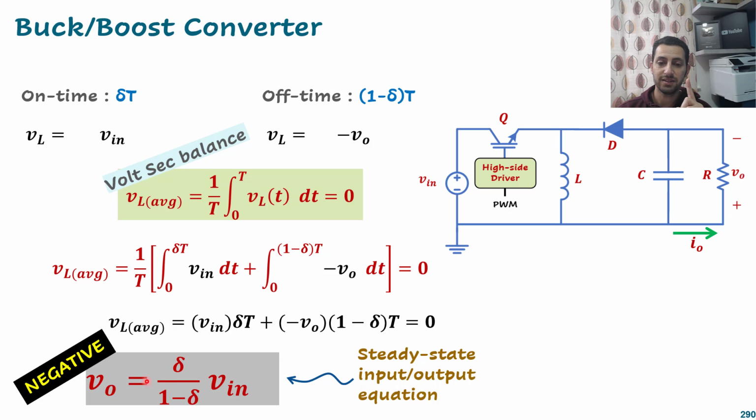And remember, I didn't put a minus here, but remember it's negative. Why didn't I put a minus here? Because we assigned the positive there and negative there. So it's positive if we consider the polarity like this. But if we consider the polarity on the opposite side, positive there and negative there, we should put a minus. So remember, the V output always has a reverse polarity compared with the input. That's why I have this big note, and you can really get the minus here if you consider positive there and negative there.